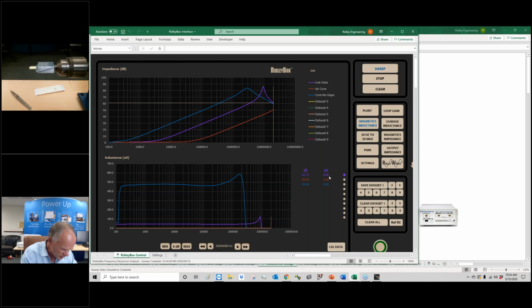And you know, if you ran the simulation with a 44 microhenry versus a 47 microhenry, you really wouldn't see any difference. What am I doing now? I'm putting tape around the core here to hold it together. Same yellow tape because I know it's got good temperature rating. I'm not using core clips.